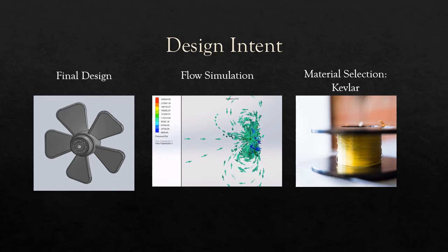After designing the propeller, the next step was to perform a flow simulation using SolidWorks to calculate the ability to produce thrust. The new design produced a thrust of approximately 940 newtons. The only concern is that the air flows in but does not flow out of the propeller. The exact cause of this behavior is unknown, but our team recognizes that factors such as blade geometry, blade dimensions, and pitch angle should be examined to improve the performance.